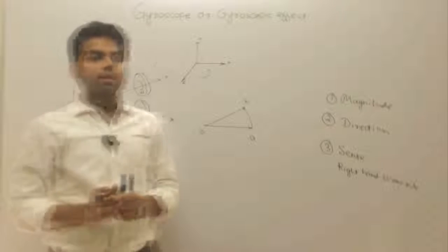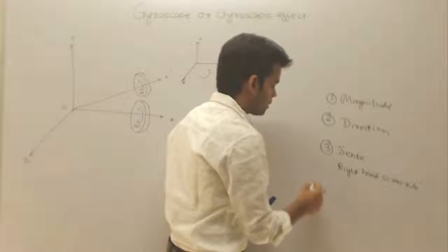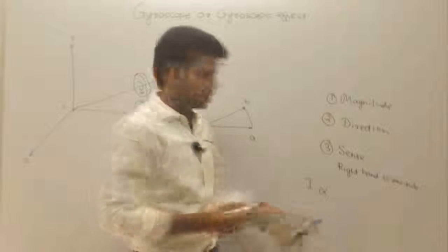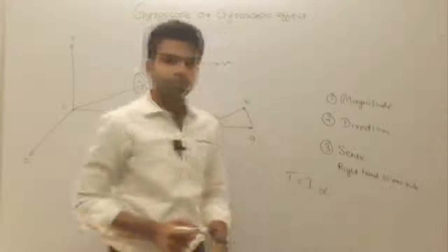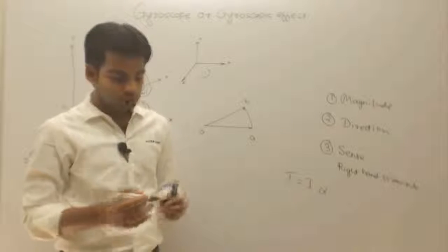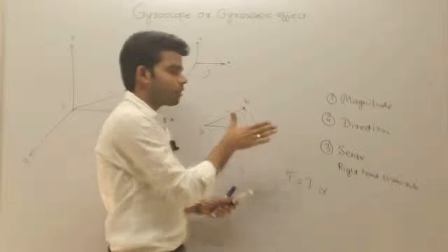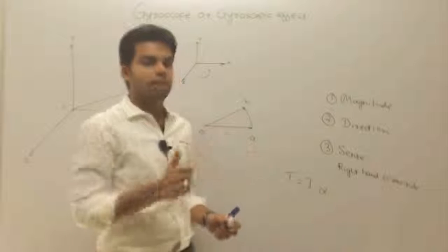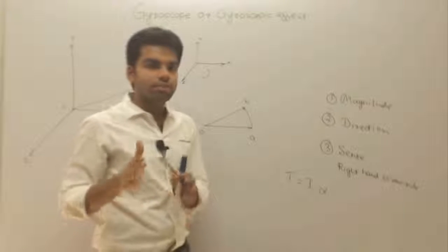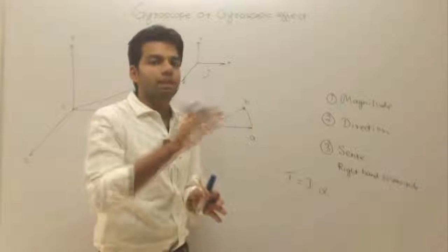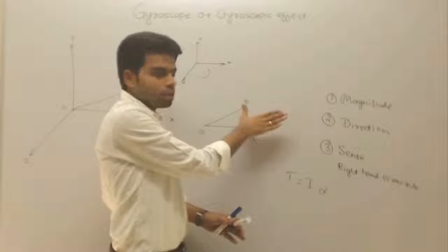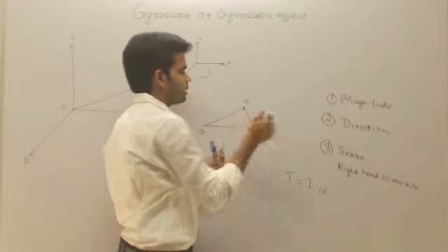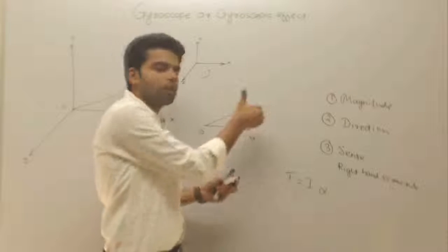Now whenever there is angular acceleration alpha, and the rotor has some certain mass, this means a torque will develop. And how can we determine the direction of the torque? Same with the right hand rule. The direction of angular acceleration will be the same as that of the change in angular velocity. That means the sense will be the same. The direction of torque will be in the direction of this curled finger, like this.